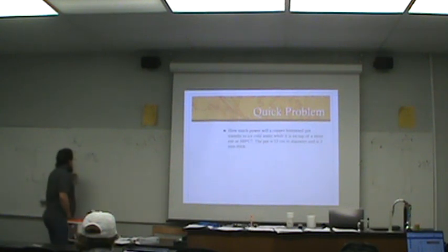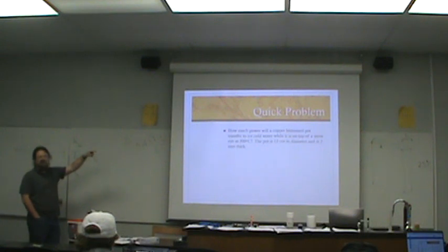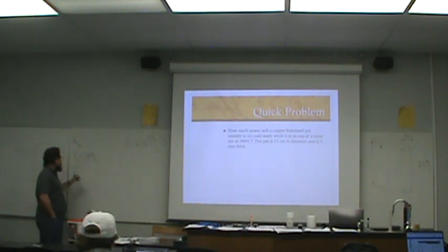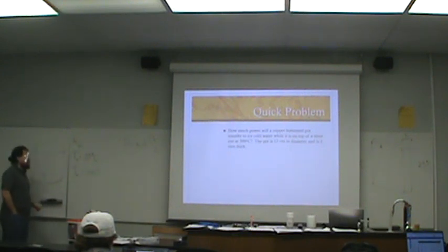We know that the hot side, the stove eye, is the hot side. The actual heating element is commonly called a stove eye, if you haven't heard that term before. So the actual hot element that the pot is sitting on top of is 300 degrees Celsius. So conveniently, the delta T is going to just be 300. That's nice and easy to calculate.